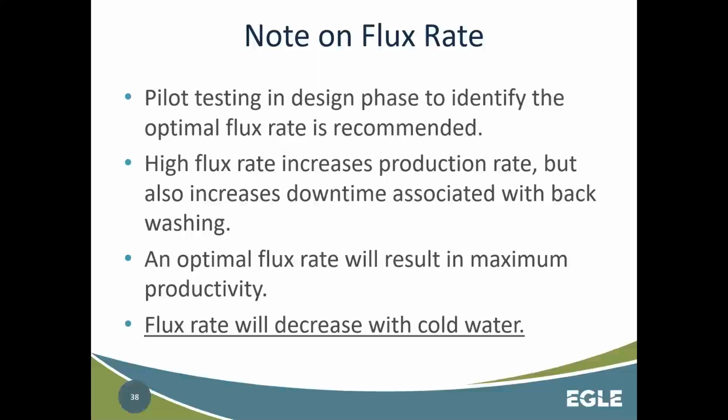And there's actually a term for it called critical flux, and that's defined as the point at which a small increase in flux will result in a large decrease in filter runtime. So once you get to that point, you don't want to run it any further. But again, this is not something that operators generally need to worry about on a daily basis. This is more of a design thing that the manufacturer will recommend for operators.